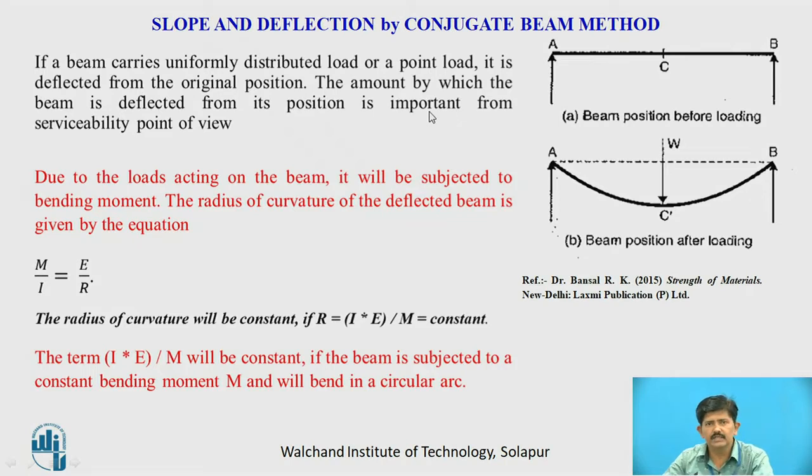See, if we are sitting in a room and the beam above it has bent a lot and there is a lot of deflection in that, we are uncomfortable to sit in that room. So, from the serviceability point of view, this deflection calculation and slope calculation is an important factor.